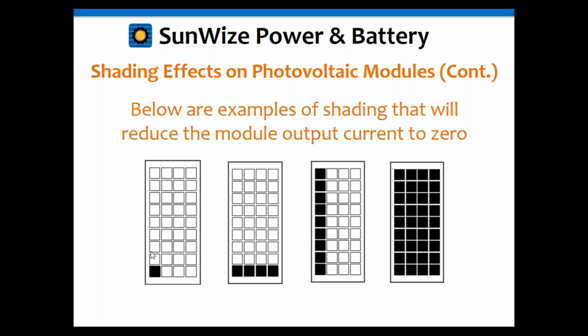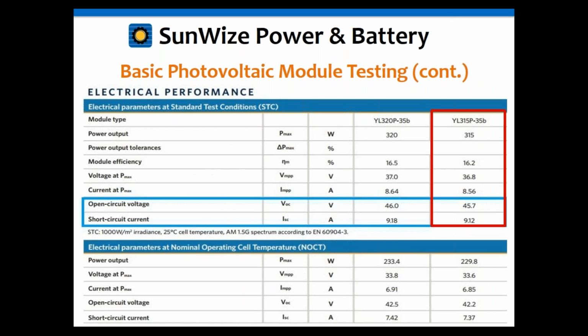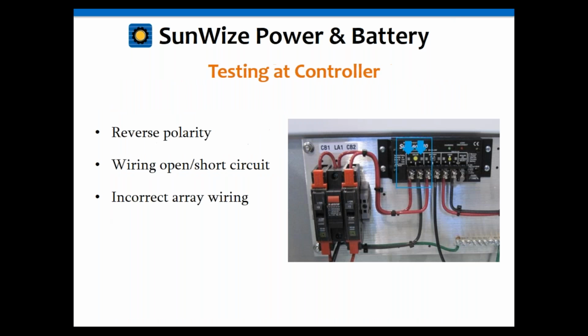If you get a 0 voltage out, what's typically happened is that one of the little interconnects inside has failed, especially in an older module, from thermal cycling. All that expansion and contraction is putting stress on all the little interconnections that connect these things together. And then they can just kind of fail over time, and generally they'll fail open, and you'll get that zero VOC on the output. So that's a common problem on older modules.